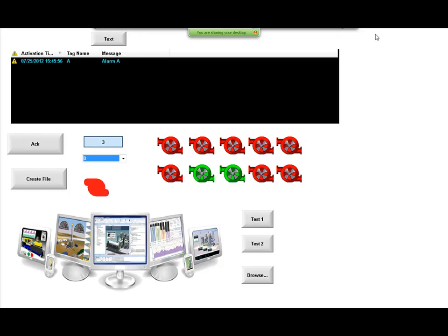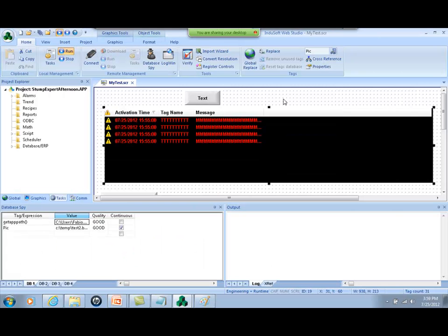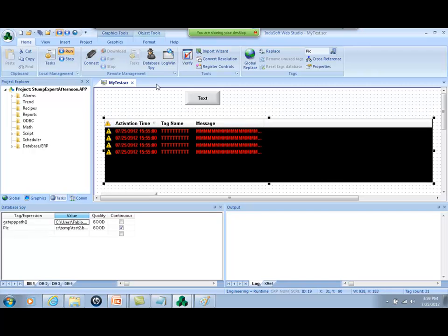How do I use the scheduler to create a delay for the tags? There are two ways to create delays. Many times you want to trigger an action, wait a period of time, and then execute another action. For instance, you click a button, set a tag, wait for, let's say, 3 seconds, and then reset this tag. There are at least two different ways of doing that.